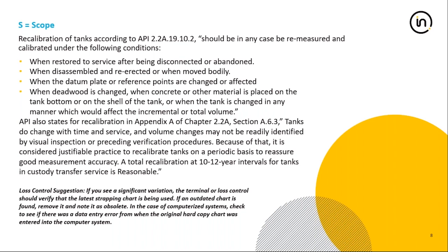This is also a loss control suggestion: if you experience significant variation or you are experiencing significant, continual losses, you should verify that your personnel or your inventory software is using the latest strapping chart, because sometimes it can happen that you are using an incorrect gauging table, and then you are wasting some of the work that you've been doing by recalibrating the tank.